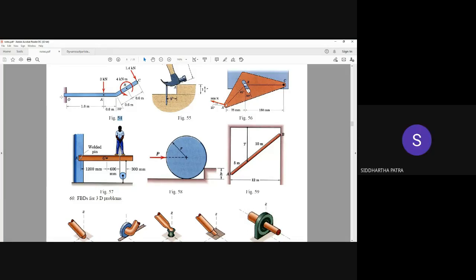So at O, it is fixed, and everything else in the diagram remains the same. For the free body diagram, I would remove this fixed support right here and substitute it with the reactions that this fixed support is supposed to provide, which prevent any sort of motion: two reaction forces and one reaction moment, directly applied at O. And then comes getting the equivalent force system.